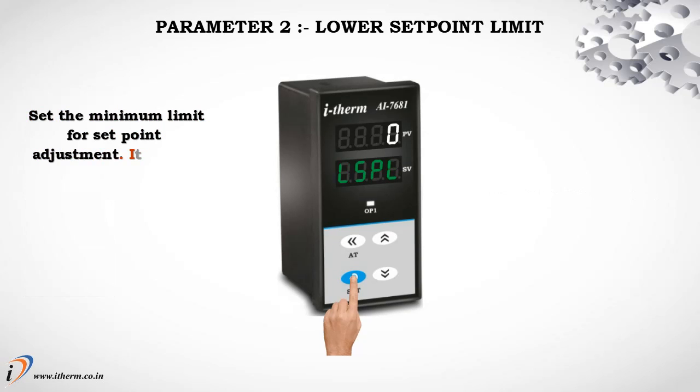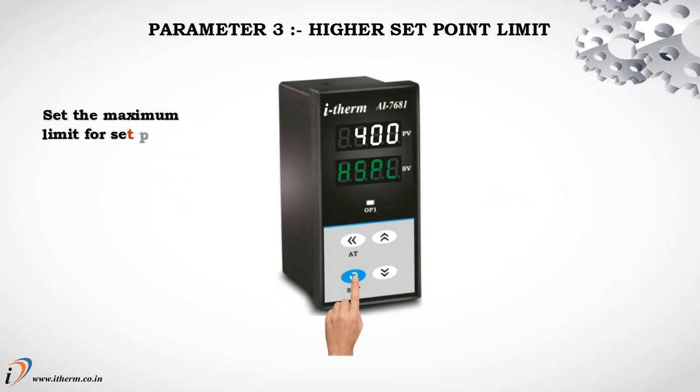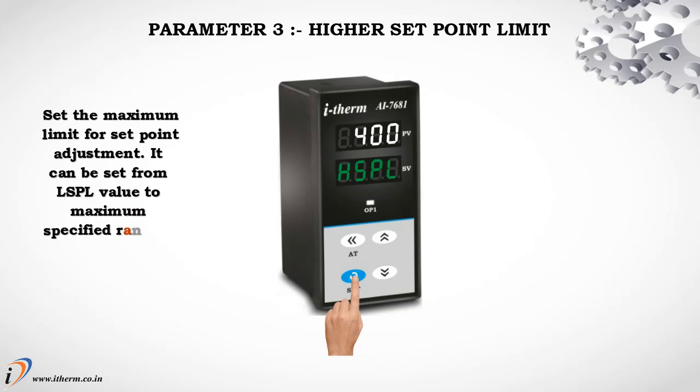Parameter 2, lower set point limit. Set the minimum limit for set point adjustment. It can be set from minimum specified range of selected sensor to HSPL value. Default LSPL value is 0. Parameter 3, higher set point limit. Set the maximum limit for set point adjustment. It can be set from LSPL value to maximum specified range of selected sensor. Default HSPL value is 400.